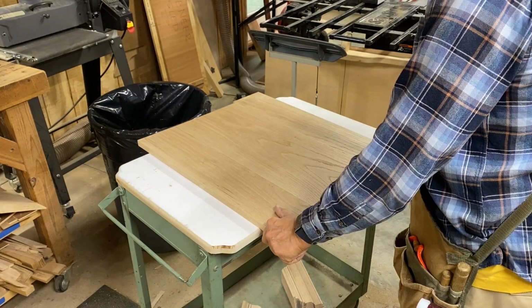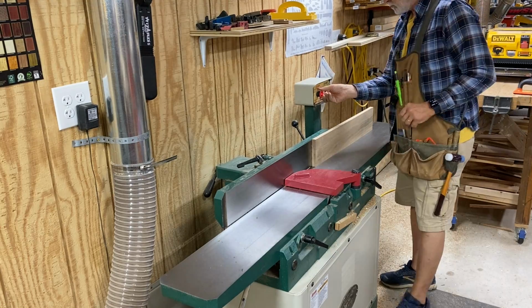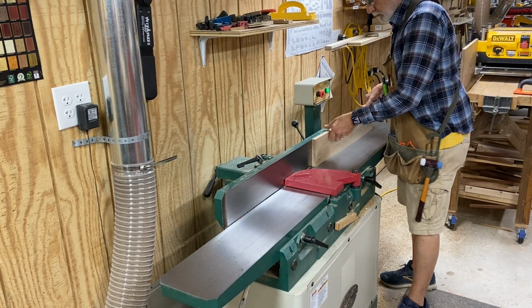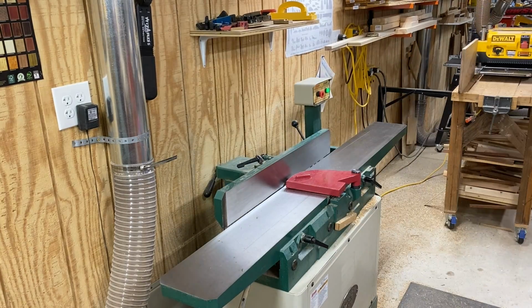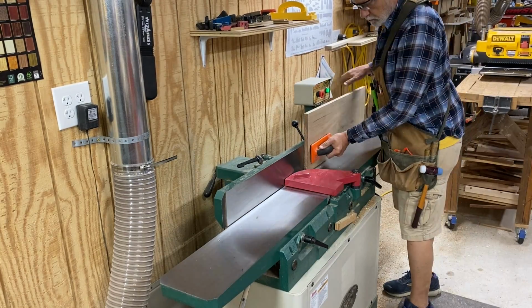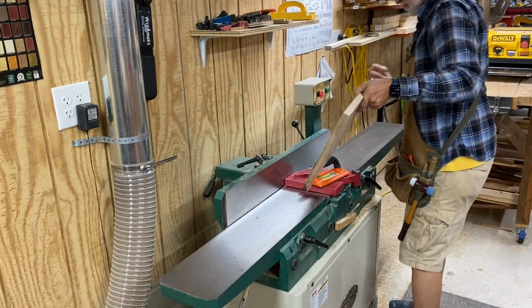There's a few special situations I'd like to go over. The first is using offset jointing to assure that tabletops will glue up dead flat, insofar as the joinery is concerned. Lay out your boards and bring 2 adjoining boards together like closing a book. Then joint the edges separately as they are held together. This negates any variance of your fence not being precisely at 90 degrees.